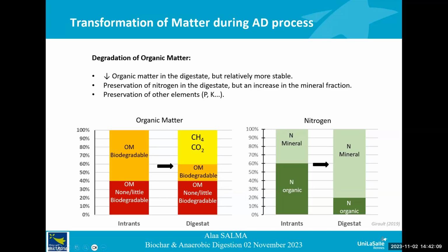So different types of organic materials and varying fermentation conditions can result in digestate with distinct nutrient content, pH level, and overall composition. Digestate often contains a variety of nutrients, including nitrogen, phosphorus, and potassium. Also, it contains inhibitory substances such as volatile fatty acids, ammonia, and hydrogen sulfide, which can accumulate when digestate is reused. These substances can be detrimental to the anaerobic digestion process and require additional process control or treatment.